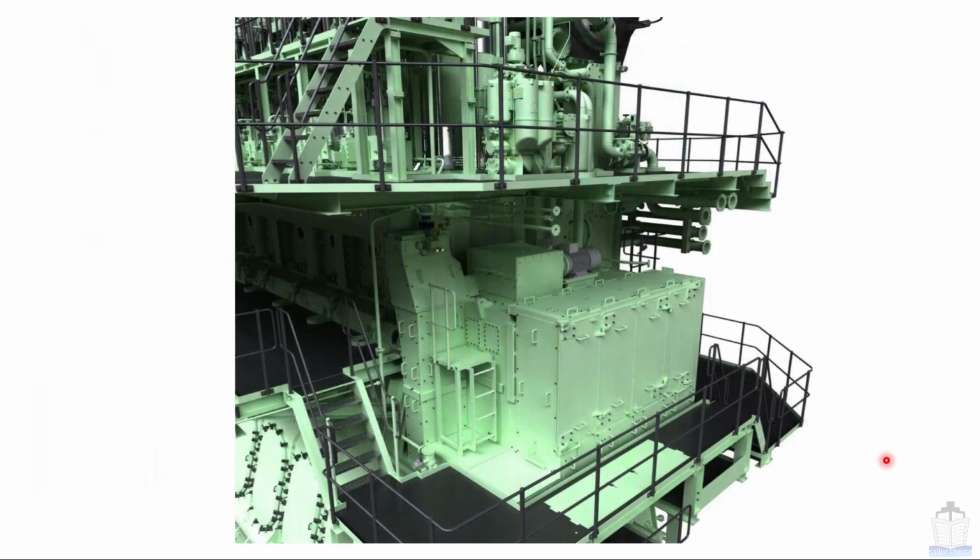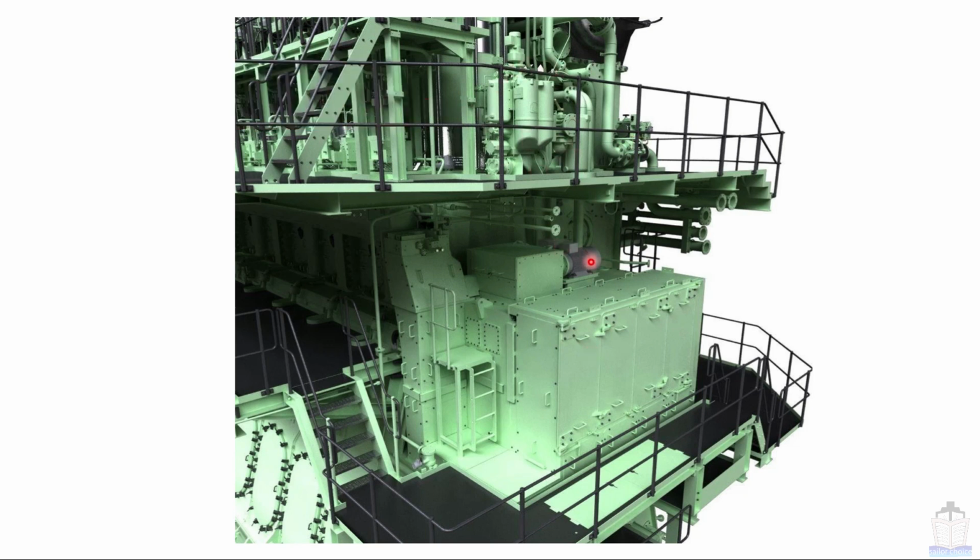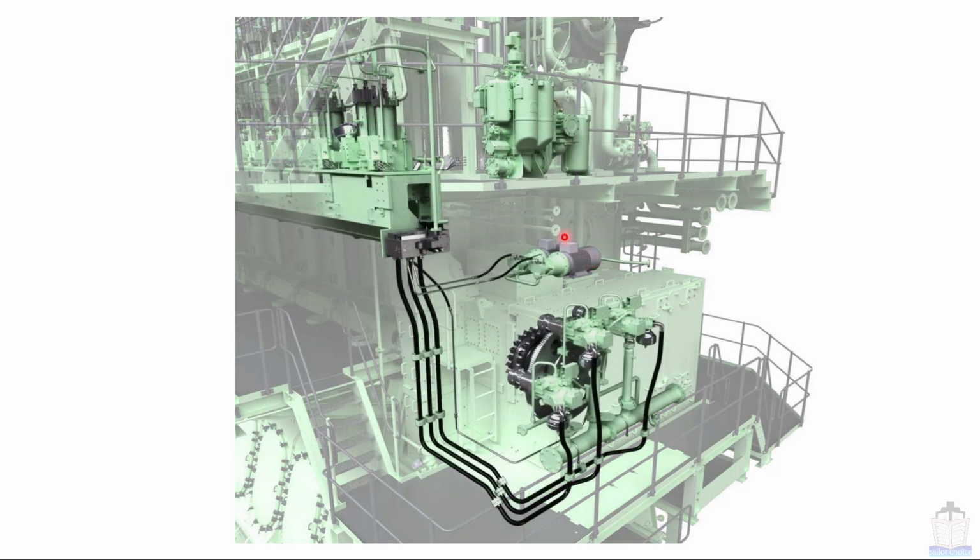Now moving next, you will find this sort of arrangement, which is shown here in this picture beautifully. This is the HPS auto filter unit. Here these two electrically driven starter pumps are situated. Now you can see how the construction actually is. This is driven by the chain. This is the step up gear, and these three are HPS pumps. These two are electrically driven starter pumps, and all the high pressure lines go to this safety block unit, and then from here it is distributed to all hydraulic cylinder units.